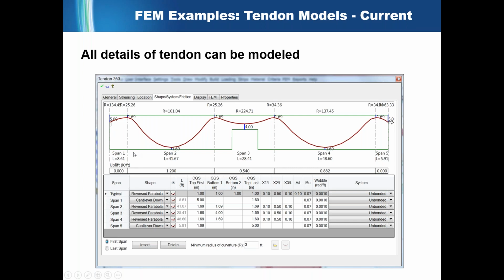And here, for example, you have a section. This looks like a slab or beam section without supports, but there's a notch in the center of this slab here. So if you're using some other solution, it might be difficult to see where your CG point is referencing. And so here it's very, very clear. You can see exactly what you're referencing off of, what point of the slab is 4 inches away from your PT. And so that's really important that you have that transparency.